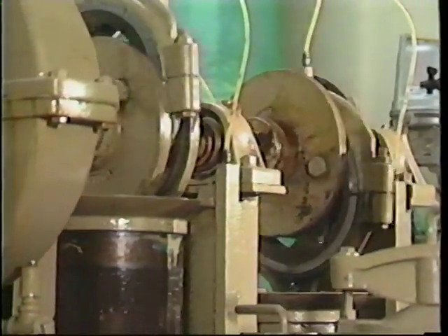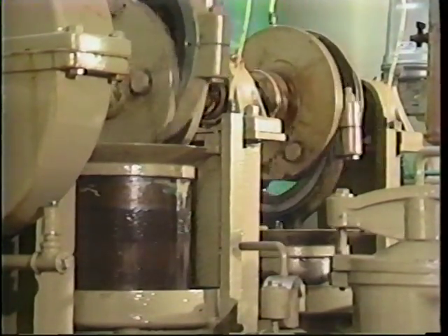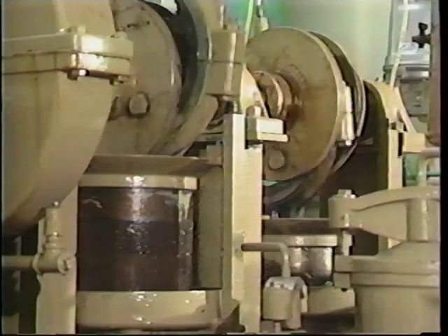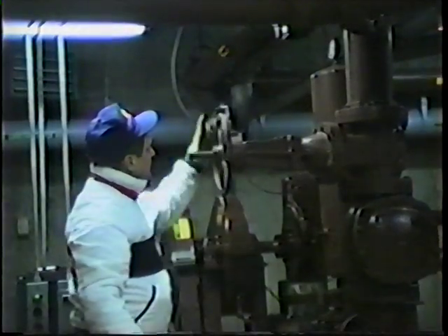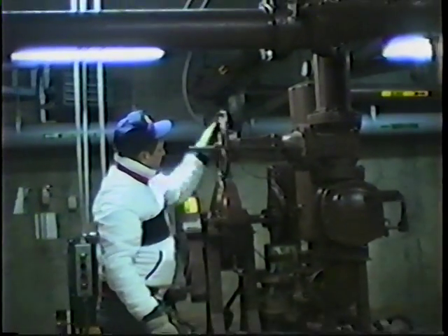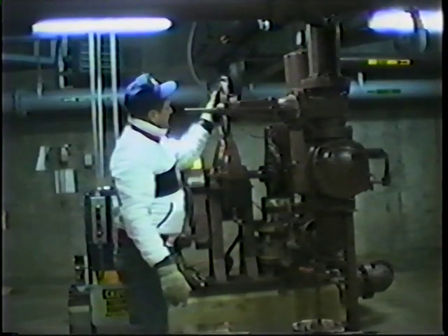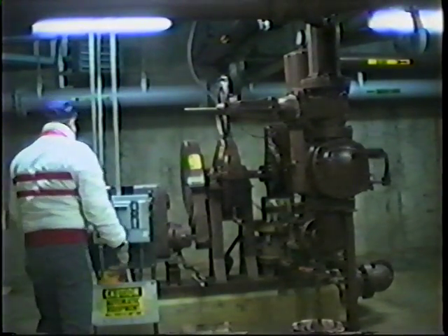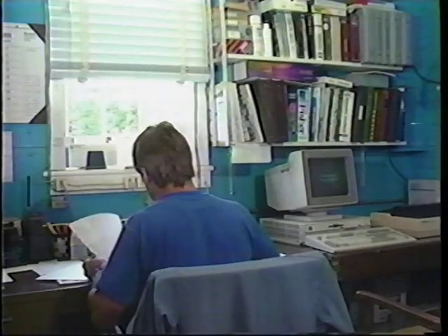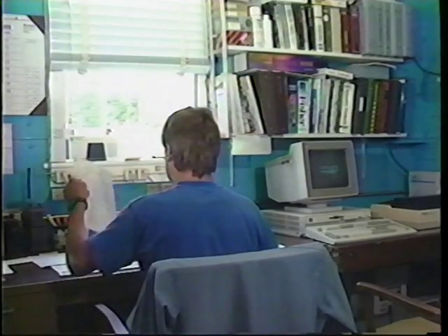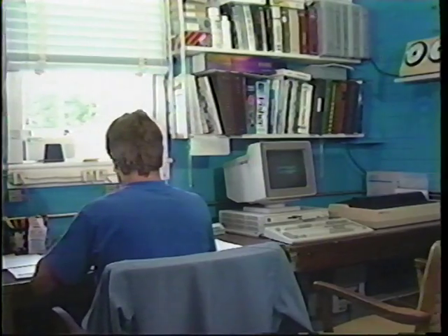Most commonly, primary sludges are removed from clarifiers with a positive displacement type of pump. The most common type of pump used for this purpose today is the piston pump. It is important to note that you must have all the necessary valves open before starting a positive displacement pump. Failure to do so will result in serious damage to the pump or to the piping system. As with all equipment, you need to become familiar with the unit by reading and understanding the operating instructions before you attempt to operate that equipment.